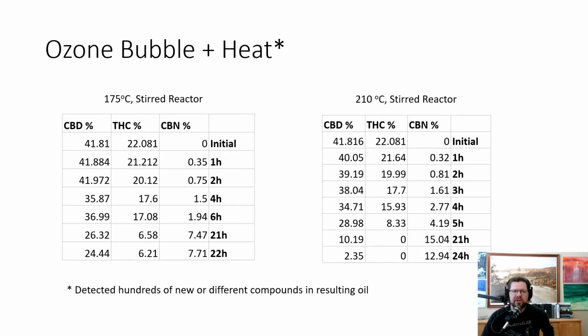So advanced oxidation processes are well known in industry. Oftentimes they're combinations of heavily oxidating compounds or light, for example, UV light, high energy compounds, and heat in some sort of an exchange process. So in this case, we've looked at ozone. We've also looked at UV light. And sure enough, it definitely will do the job. I mean, it will take out the THC, but you'll also see that there are side reactions that occur. It's not stoichiometric, meaning there are other things that are happening.